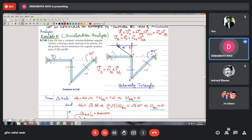Second thing, what I want to do is I must find out the velocity of point B also. So the velocity of point B is root 2 times either of these two velocities. And this point's velocity must be equal to omega of this member into the length of this member. Now the length of this member is root 2 r, so it is root 2 r multiplied by omega BC, and that must be equal to this velocity. So you see from here you get omega BC is also equal to omega. So that's nice. Now what will be their directions, I mean to say their sense.